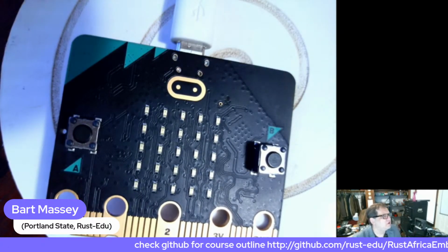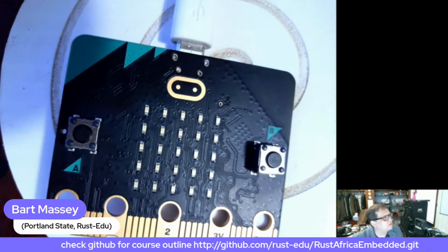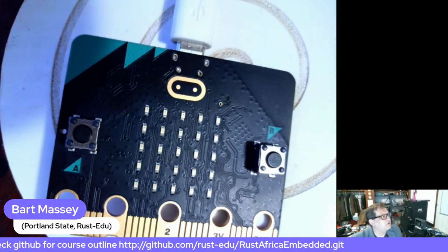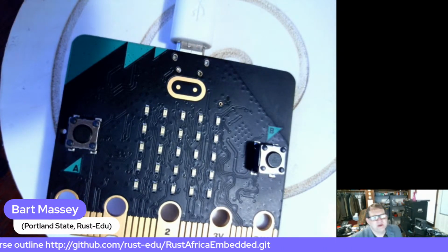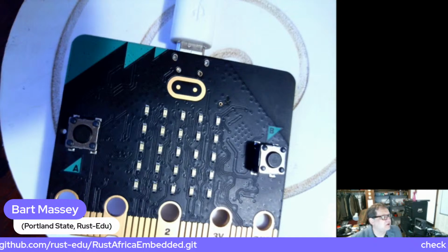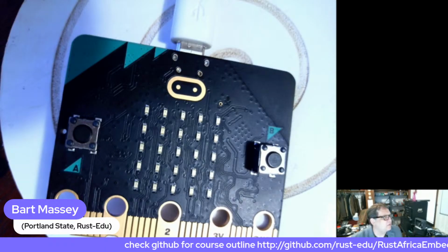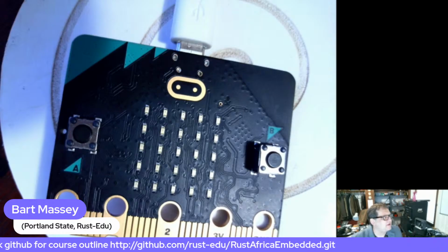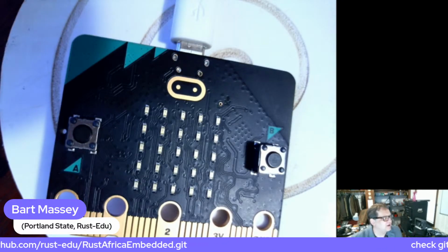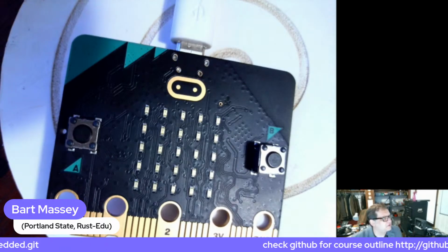But what we're going to do is use our normal entry point. We're going to use the input pin trait from the digital embedded HAL traits. That just lets us do this. And the microbit board support package, the usual panic. This is a panic that prints the panic message out on the console, but we're not going to get any panics, so it won't matter. And then this normal stuff so we can print stuff.